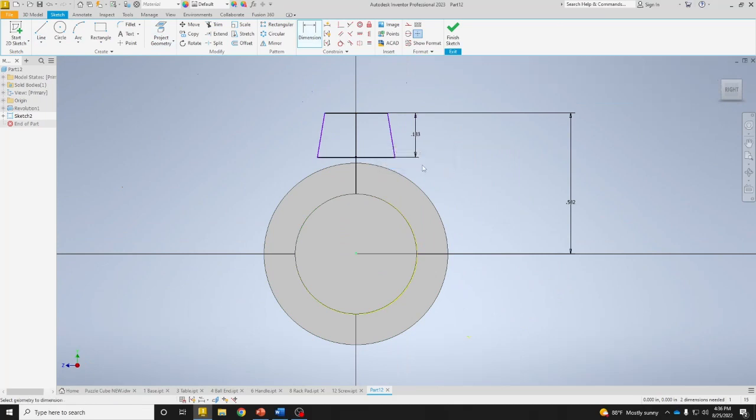The next set of information that we need to put in is our pressure angle. The pressure angle is where the two teeth of a gear or gears meet. So the pressure angle normally is from this angled surface to the center of the tooth, but unfortunately for this drawing, it's incorrect, and it should be from angled line to angled line, and this should be 20.